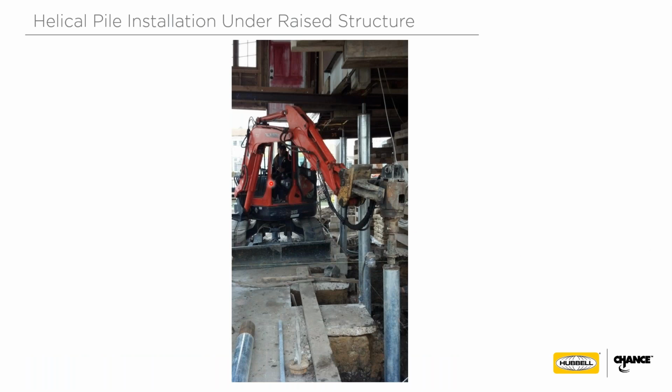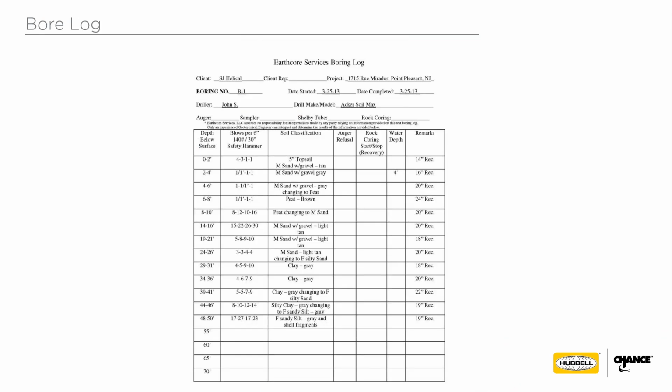You see this mini excavator rig. He's installing the helical pile right here. He happens to be directly under the chimney at this point, which is always interesting when you're standing there directly under chimneys of a structure. But that's the way this is done. So you can see some of the attributes of helicals in that respect is it's not going to be easy to drive piles with a pile driving rig with that type of situation.